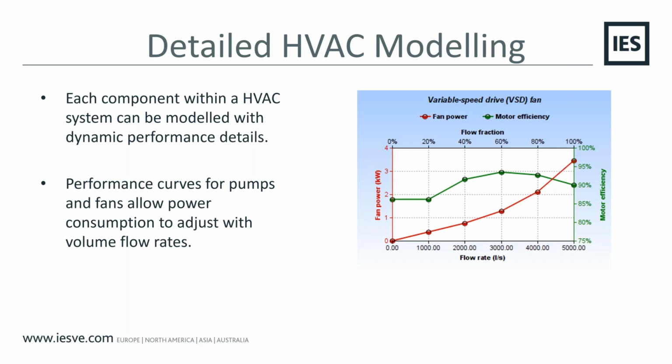Okay. As the fans are explicitly modeled, designers can experiment with different configurations of their HVAC systems to understand how relatively small changes in the design can affect the performance. One example of this might be with a fan coil unit installation. This could potentially be configured to have fresh air coming onto the back of the unit, or with a separate ventilation supply going into the room.